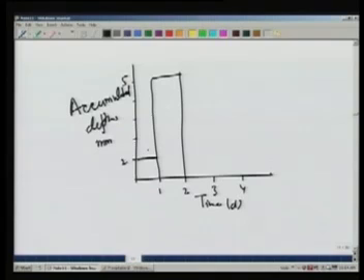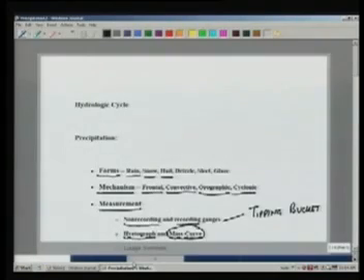So this curve is continuously increasing because it tells you the accumulated mass or depth of rainfall. For recording gauges, we typically get a curve which directly gives us the accumulated depth. In the recording gauge, the tipping bucket we have seen, but there's another one which is not so common because it's more expensive, and which is known as a weighing type.